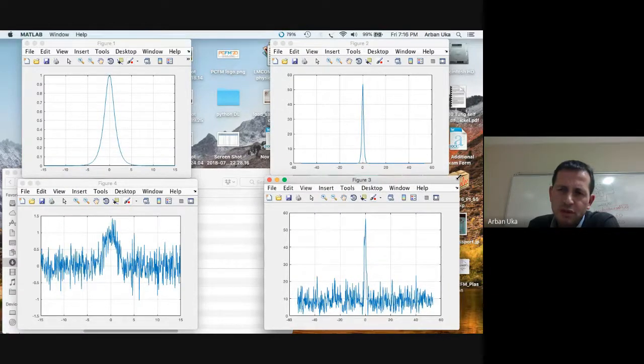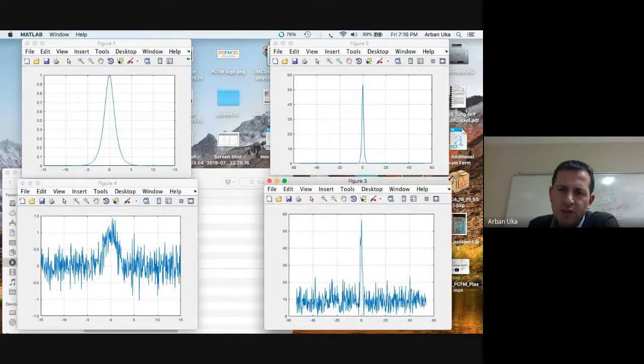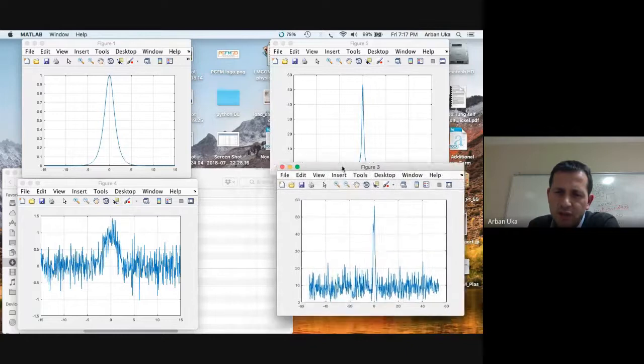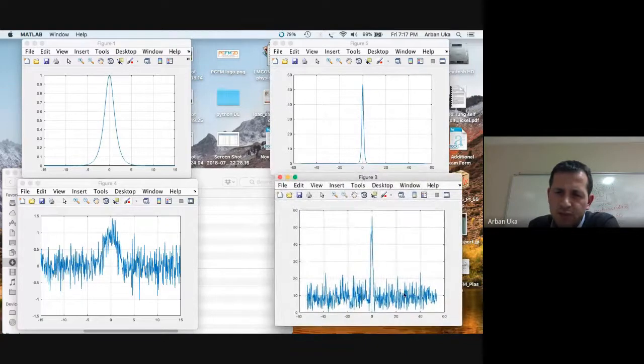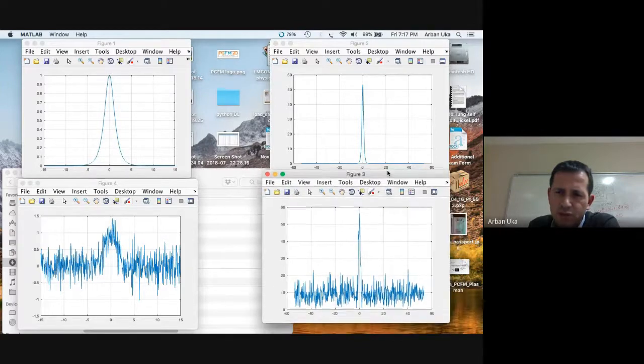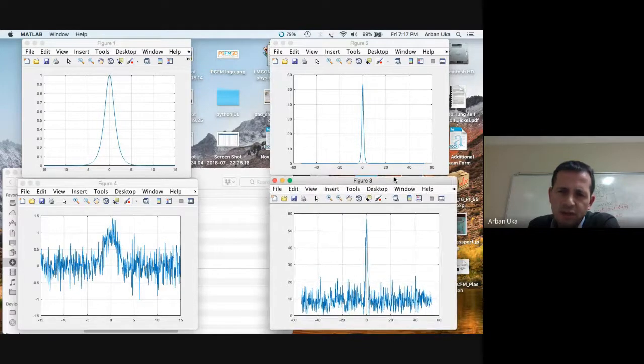But we are going to see also cases of how we can apply a notch filter. With a notch filter, we can erase a specific frequency. So for example, if we see this figure here, we can try to filter out these frequencies from 20 to 40. This range here from 20 to 40, we can filter out by applying a notch filter. Notch filters are traditionally very narrow filters, so you clear out a specific frequency.